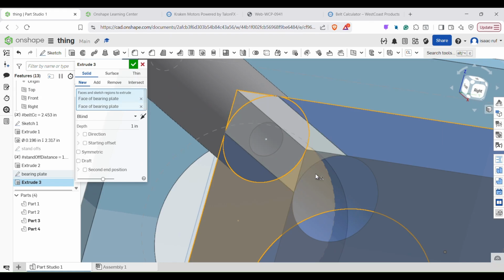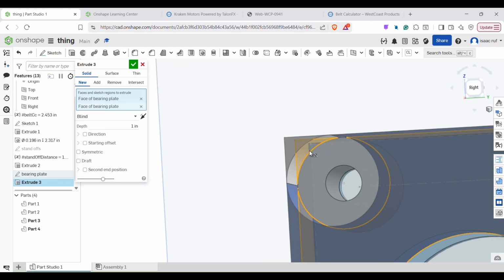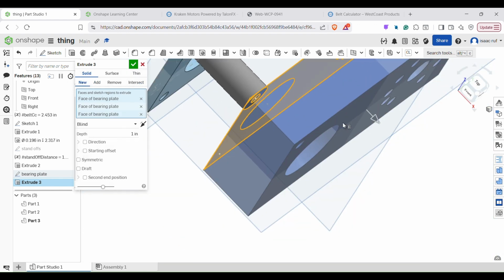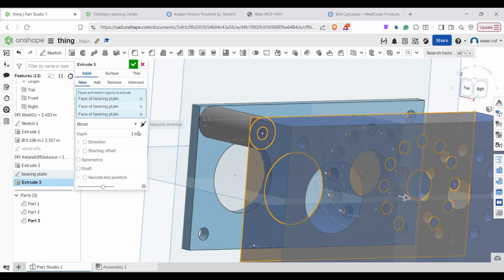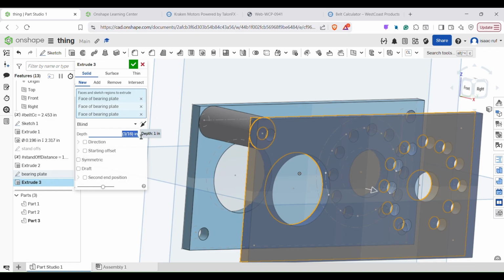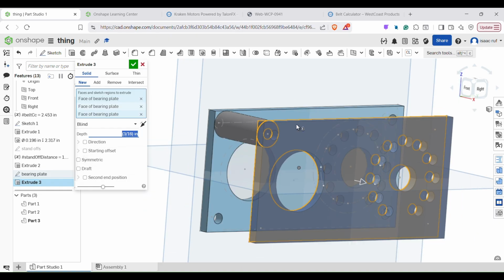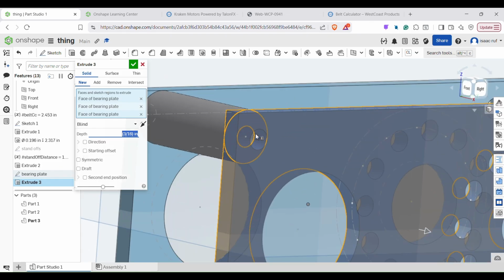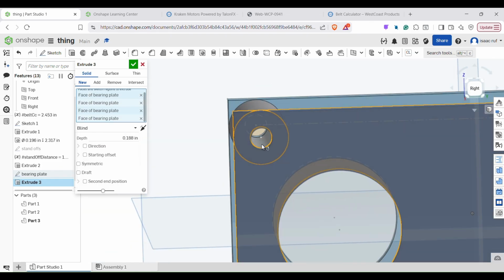So we're just going to go ahead and click this geometry. One of the ways you can get around that is hiding parts, but you're not going to worry about it. This could be a new part, and we need it to be not that thick. We want it 3/16 again. We could make a variable for this if we thought we were going to change it. Honestly, I don't think we'll change it, so it doesn't matter for what we're doing here. But yep, you'll see we have the second part. I want to actually extrude this part there too.